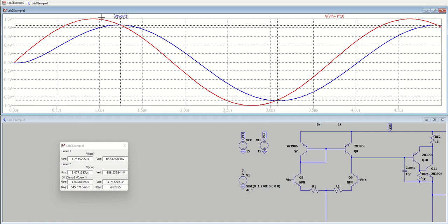And you would also get 1.8 on the upper portion. And you could see that there's a little bit of a DC component to it, so the upper portion right here is a little over 1.8, so that's why I'm doing a little less than 1.8 on the lower portion. And so once you do that, you obtain this value, which we're going to call 1.75 volts.